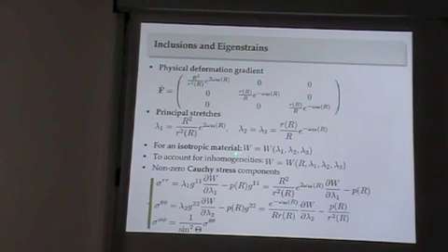Now, for an isotropic material, the energy function depends on your principal stretches, classical nonlinear elasticity. And if this is neo-Hookean, for example, it would be this one squared plus this squared minus 3, times mu divided by 2. But I'm going to solve the problem for an arbitrary energy. And not just this, it could depend on R if I have an inhomogeneous material, but yet spherically symmetric. So depending on where I am, I have a different material, but isotropic. Then I can handle that too.